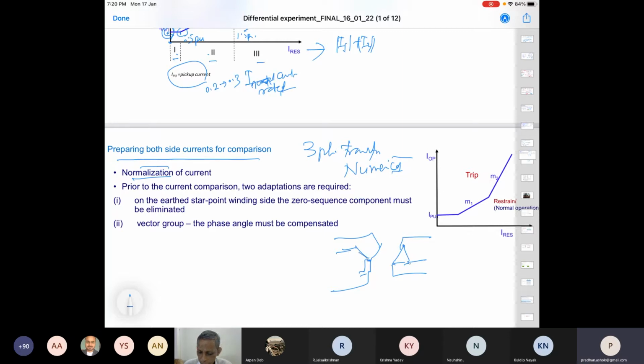This is the transformer side. The CTs are connected to the line side. You understand? CTs are connected to the line side. What is line side? Inside the transformer we will not put the CT. We are putting everything outside. So therefore, these are connected to the line side, the transmission line or distribution line to which it is being connected.